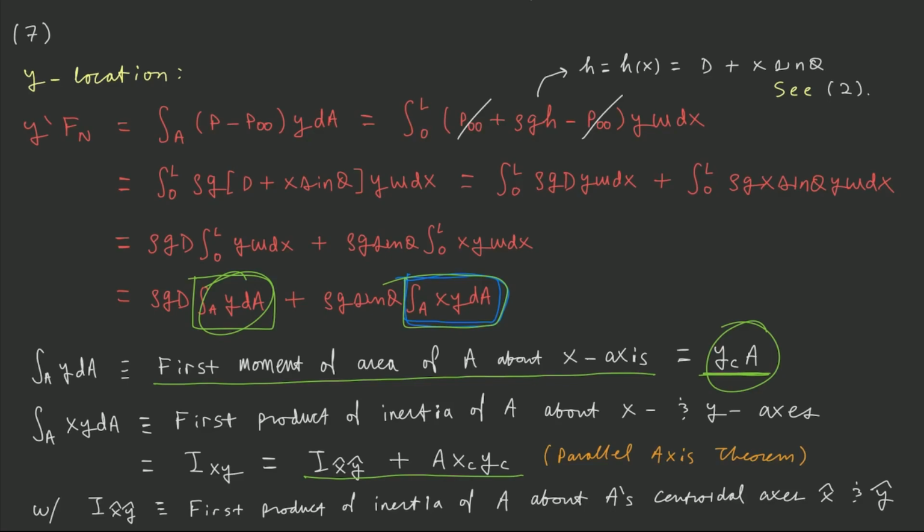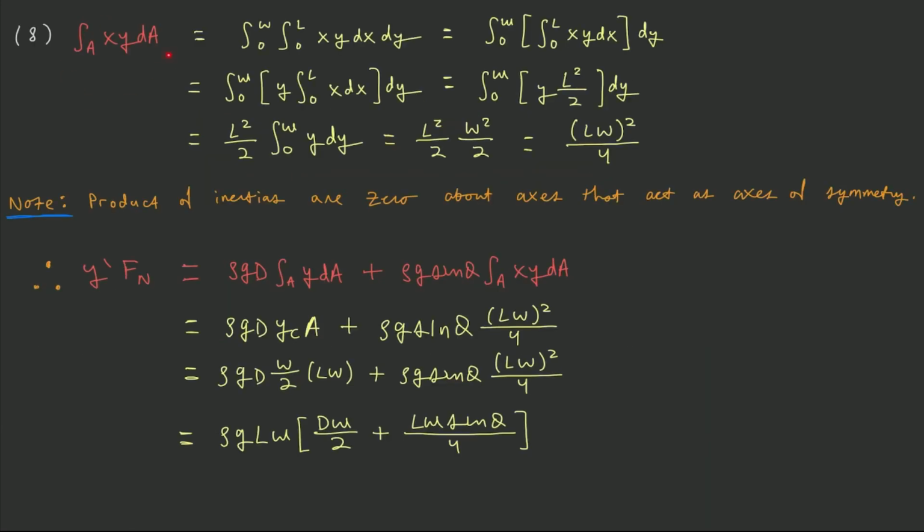However, I find it easier to just simply perform the integration on the particular shape, because this integral is usually not very hard, especially for symmetrical objects. So we're just going to perform this integration, but keep in mind, if the integration is too complex because the shape is too complex, you can use the parallel axis theorem to express this second integral as a summation of simpler terms.